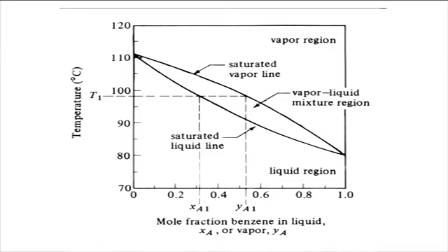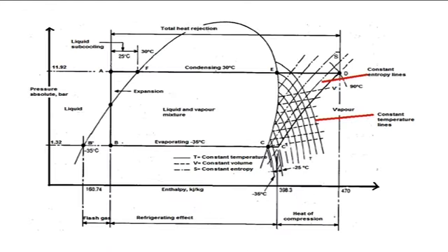There are upward sloping curves in the mixed region which indicate quality. Quality is a measure of the ratio of vapor mass to the total mass. For example, quality of 0.1 or 10%, which is located near the saturated liquid line, describes points that have 10% vapor by mass. Figure 2 represents a generalized Mollier diagram, and its various lines and regions are explained below.